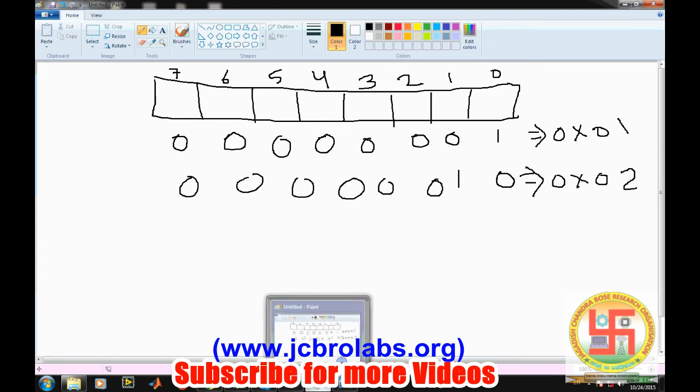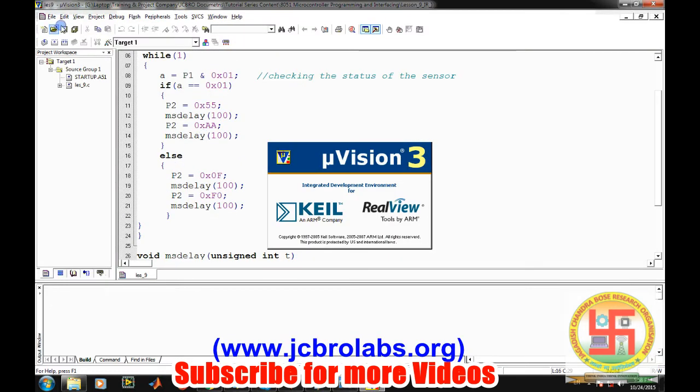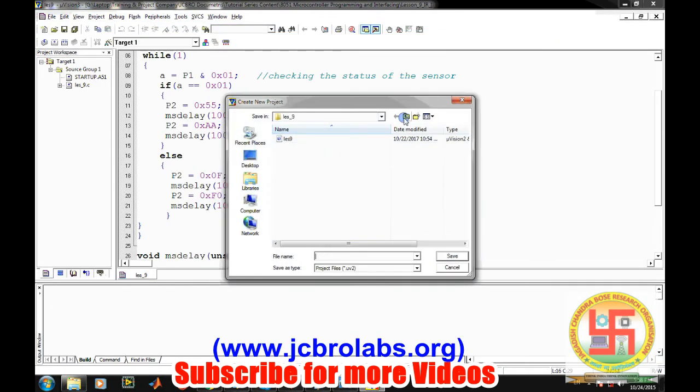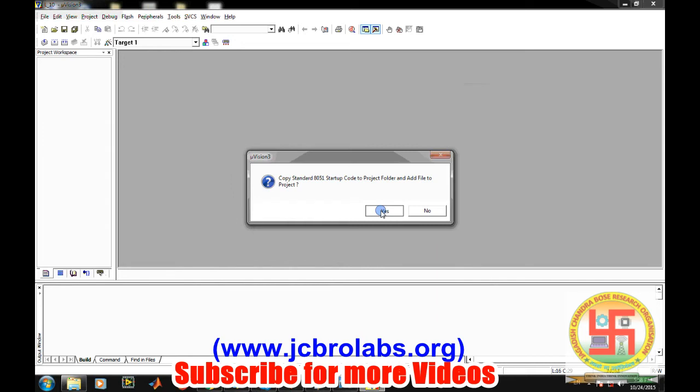So now let's write the code in Keil software. So let's open Keil and create a new microvision project. Lesson 10, create. Save, select the device, it's AT89S52, and then OK.